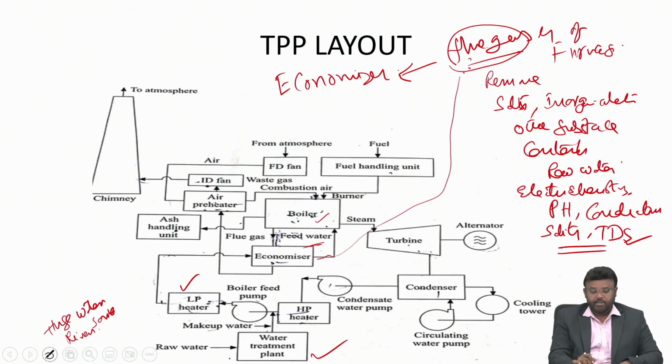So for example, the raw water is having a temperature say 26 degrees centigrade, and you can heat this up to say 50 or 60 degrees centigrade, because the temperature that we collect from the flue gases may be at that level. So extra energy only we need to supply to generate the steam. In that way we can save the fuel that is required by the water to generate the steam.